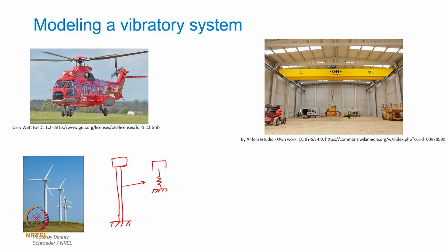So, if it is modeled like a spring having some stiffness, the mass of the nacelle sitting at the top, if this is a longitudinal vibration problem, then the stiffness has to be appropriately calculated. Now, that of course will depend upon the material properties and the shape and size of this particular column.